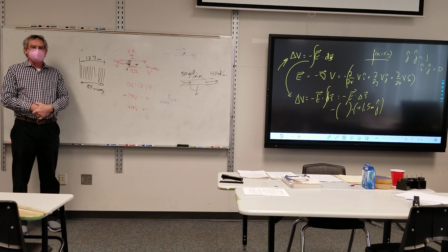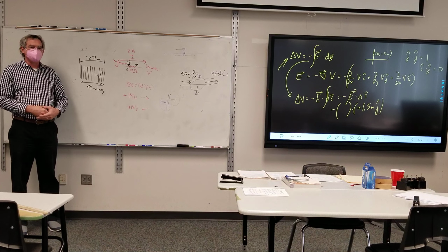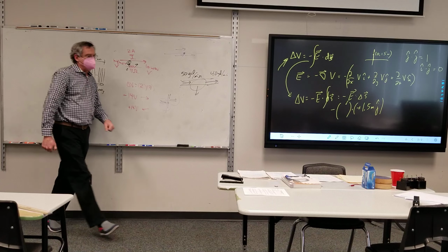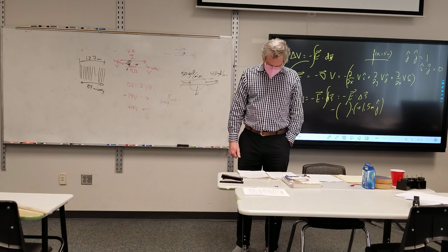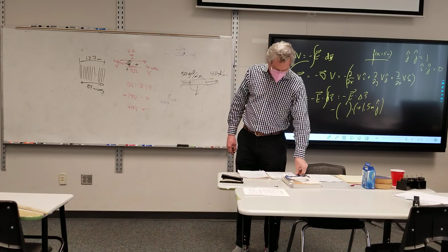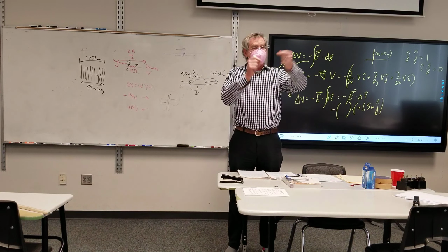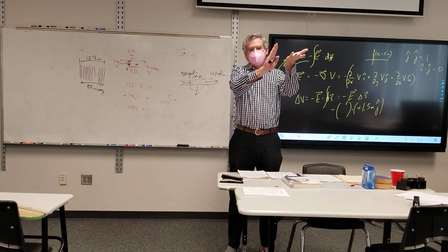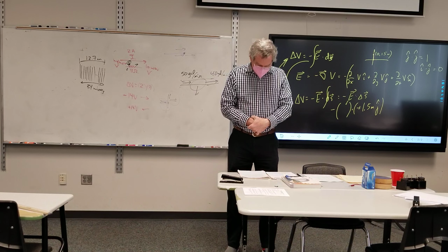You just divide everything by 34, and that'll tell you the distance per wire, the diameter per wire. And then for the cross-sectional area of the wire, think of the wire as a cylinder, so the cross-sectional area is a circle.